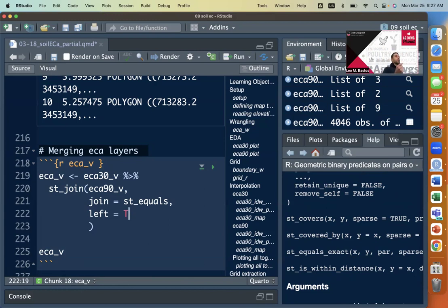We saw this when we were doing the terrain variables. If you remember, elevation had the most rows, and then when we did slope and aspect, we could not calculate slope and aspect near the border of the field because you need all neighboring cells to do that. So all the slope and aspect objects have NAs near the border, meaning they had fewer rows than elevation.